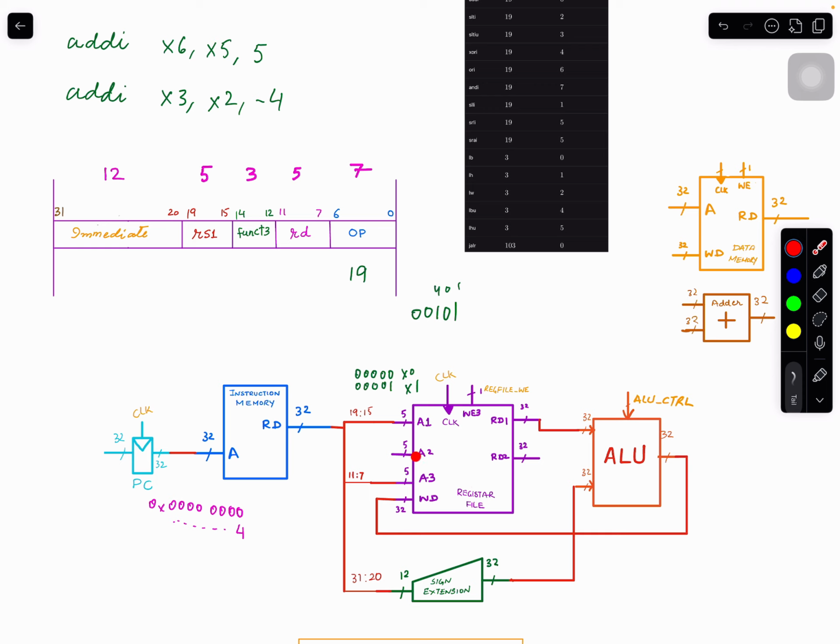Okay, so now in the register file, we have this source register that we want to read, the address here, and its value is available here. Okay, fantastic. So this value is 32-bit. Our ALU has 3 inputs. This one is deciding what this ALU is going to do: add, subtract, compare, NOR, and all those things that our ALU is capable of, right? Gradually we will add that functionality, but this is going to determine that.